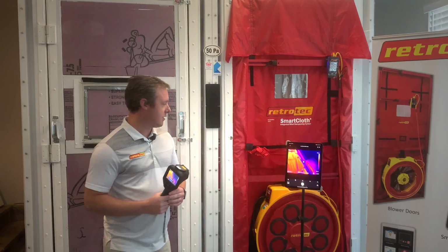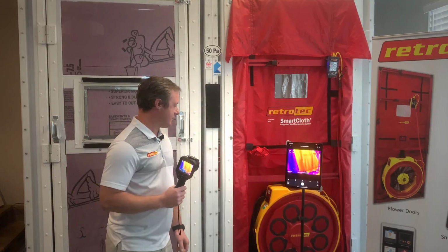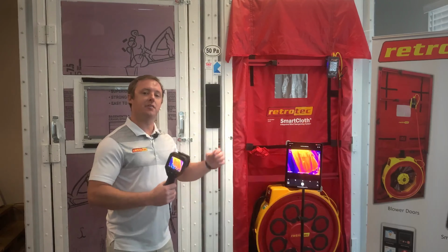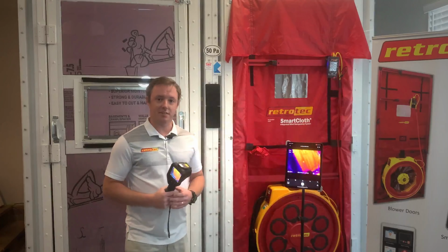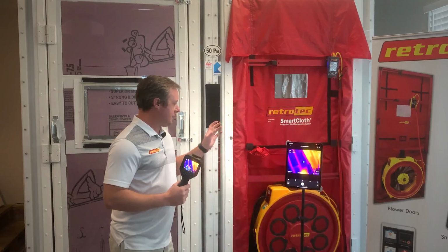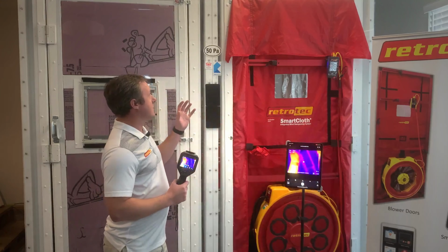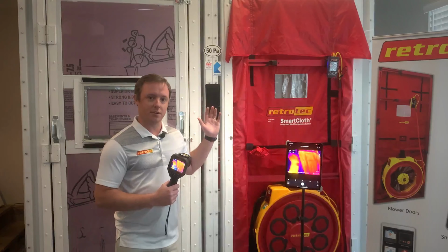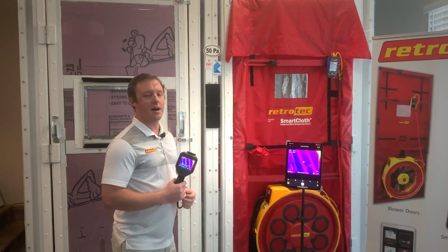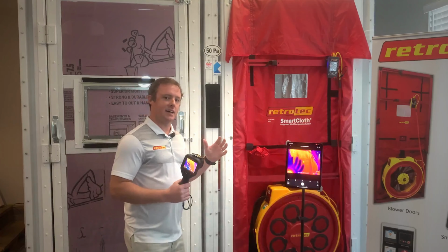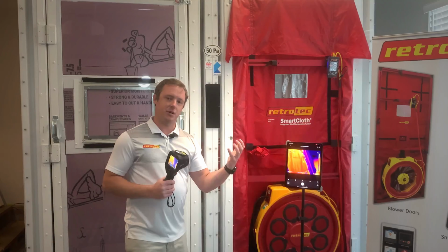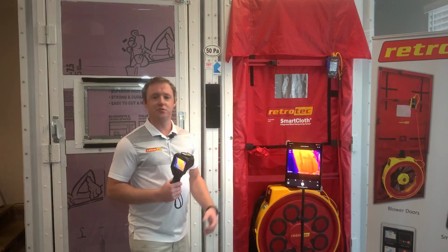So to start off with, we have our blower door set up to pressurize this space. If we are trying to capture thermal images from the outside of the building, then pressurizing is what we want to do, because we want to force some of that warmer interior air outward so we can capture it coming out of the building envelope wherever it's leaking. But for most houses, we're going to do the opposite. We'll stand inside the house and depressurize the space to bring that outdoor air in to see where it's coming inside. So in this video, I'll do both.